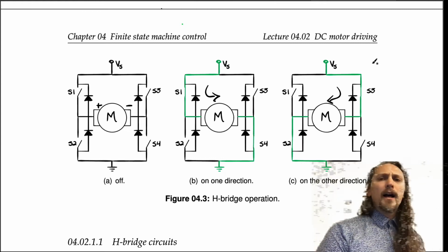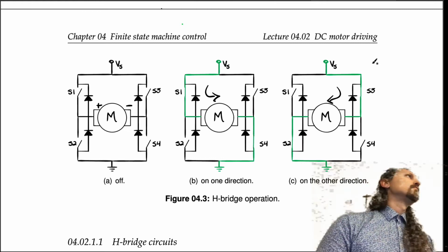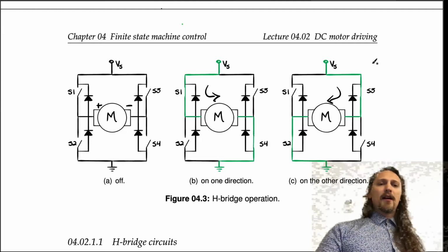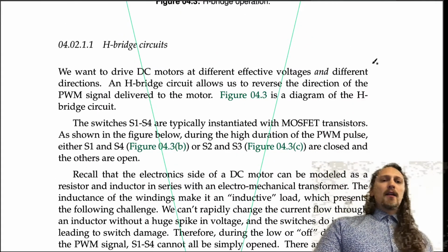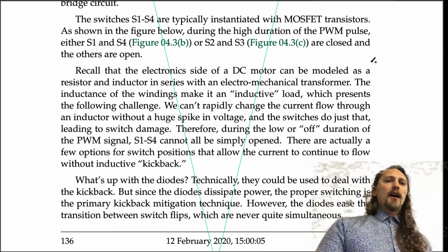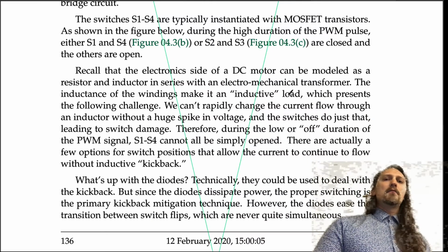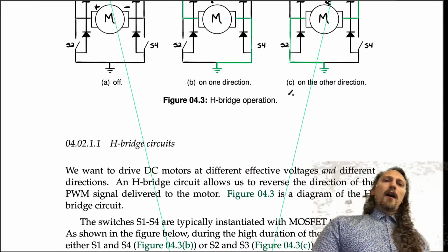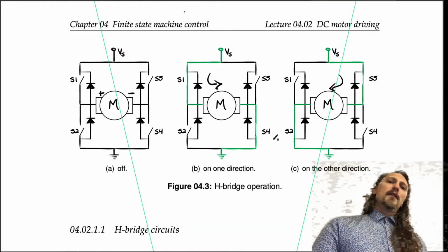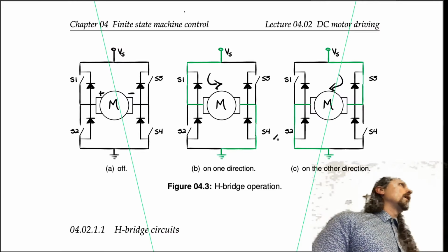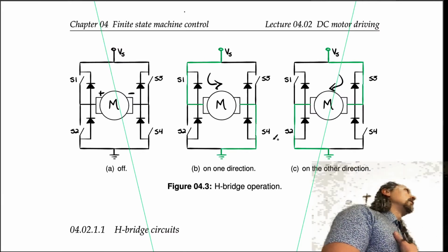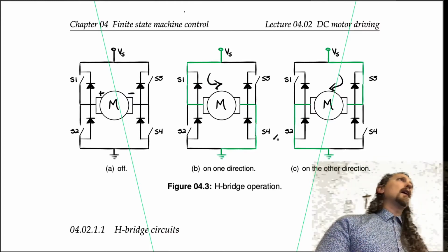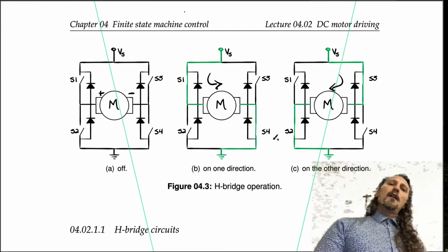So it's kind of nifty, right? It's a pretty cool setup. And another thing that can be done here is to use the diodes as a way of mitigating inductive load kickback that can happen.